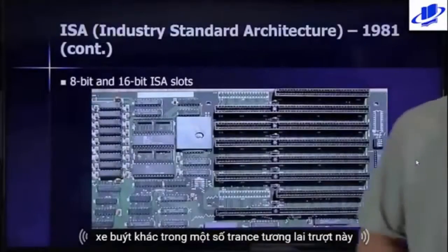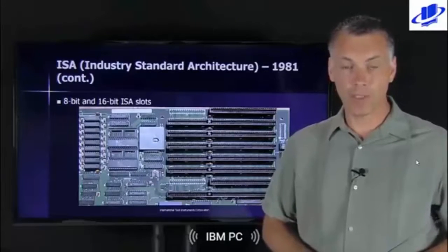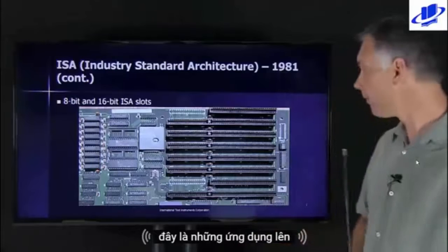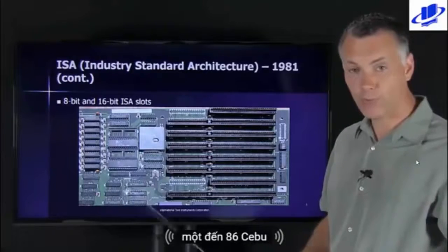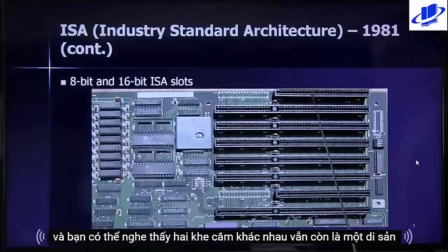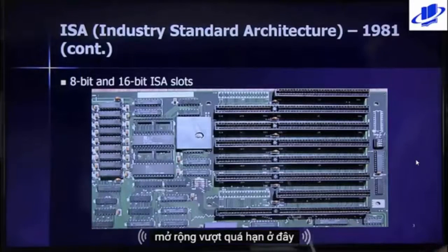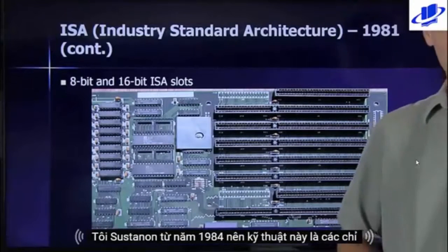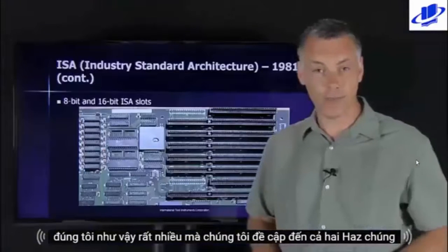This slide shows the original IBM PC-AT motherboard from 1984. This is the board that uses an 80286 CPU. And you can here see the two different slots. This is the legacy original PC slot, and this is the extended, you see the extension here, connector for the actual ISA slot, which is part of the ISA standard from 1984. So technically this is the only true ISA slot, but we refer to both as ISA slots and therefore ISA boards.